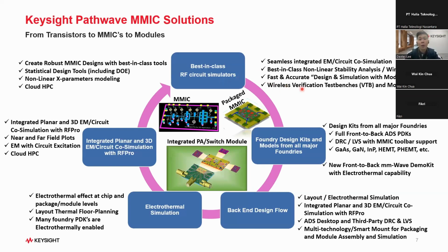Okay. We also have some of the wireless verification test benches. We call it the virtual test bench, whereby you can simulate some of the modulated signals such as Wi-Fi and 5G signals, and you can simulate across your power amplifier design to look at some of the EVM performance. So that is one feature that we'll look at later on.